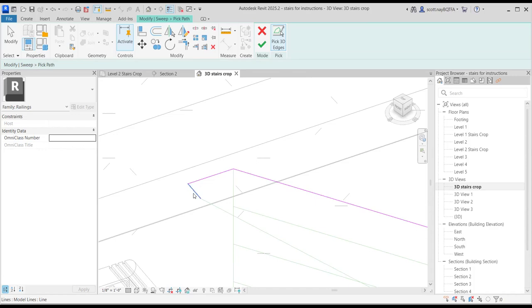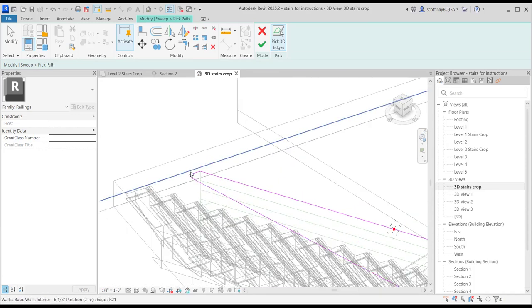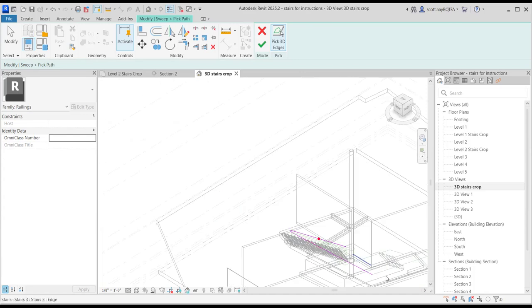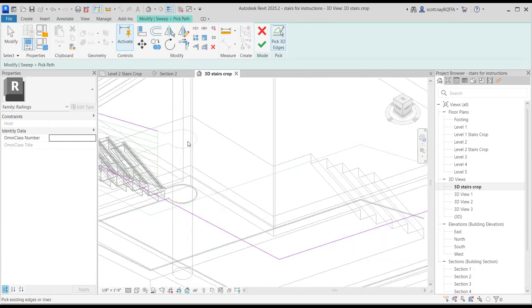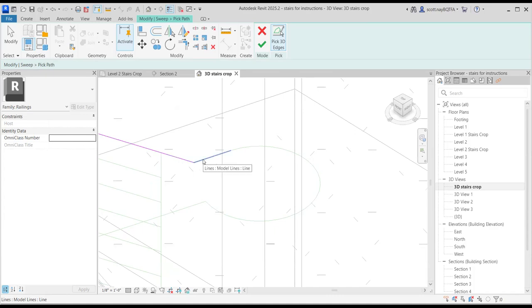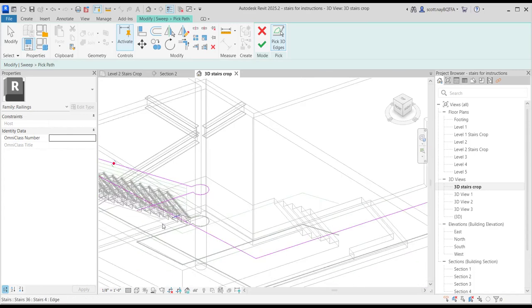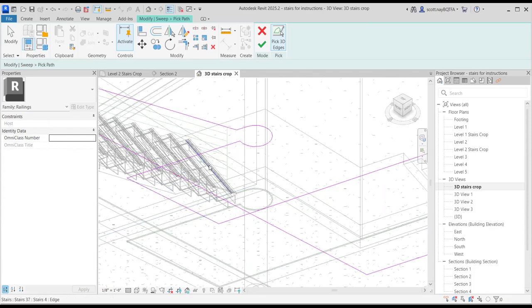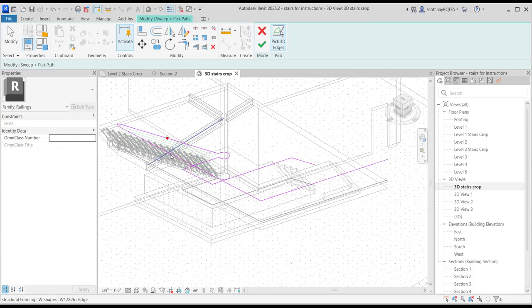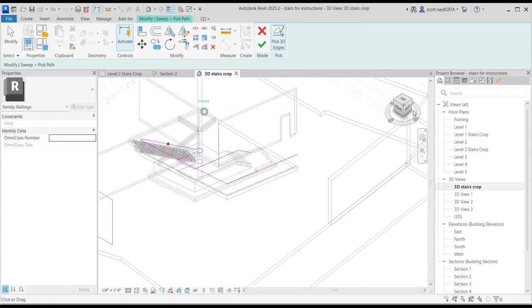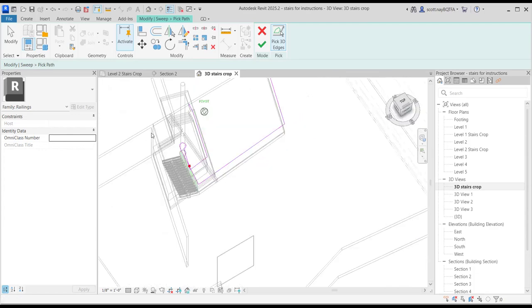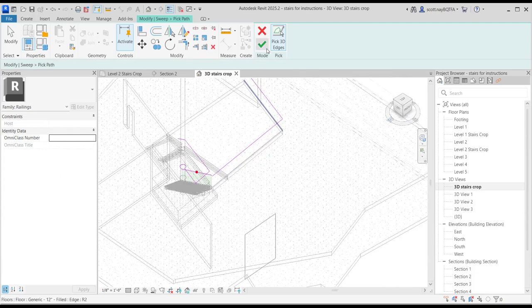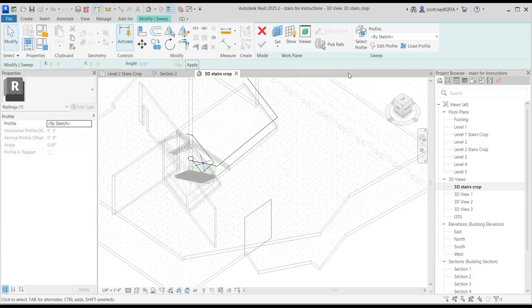Again, I flattened it out here, and that's going to keep me from not being flat, because Revit will rotate, and all of a sudden your flat top is at an angle. This is getting funky. I think that's all of it. It's easiest to move this around when you're zoomed out. I'm going to click OK. All right, it was happy.